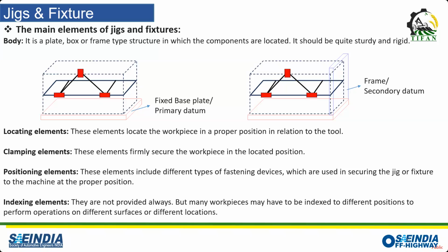Along with the rigid primary base datum, we can also use locating elements like Akshay was mentioning earlier in the hardware selection part. We can use a few dowel pins in the fixture in order to locate our workpieces, because you might be doing a lot of welding and different kinds of welding, so you might not be doing that at one place. You'll carry a part from one location to another. While doing so, when we do these multiple operations and bring it to the final assembly, we have to ensure that the position at which it was welded earlier is retained when they are completed with the manufacturing, and when we have started assembling them.